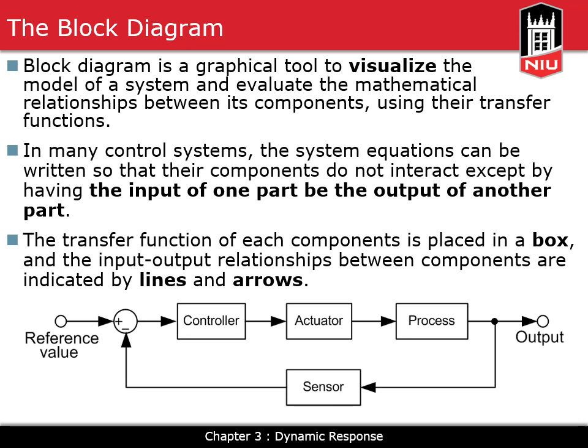Inside each of those blocks, we're going to have transfer functions. So basically, the input and output of each of the blocks will be related to each other through a transfer function in the S domain. So we'll be completely working in the S domain. It is very important to learn how the block diagrams work, which is actually the simpler part, and also how to find the transfer function of a complete block diagram, the transfer function from the input to the output.